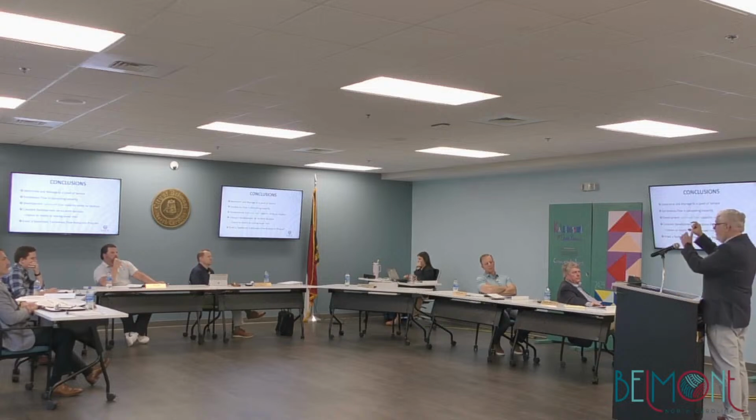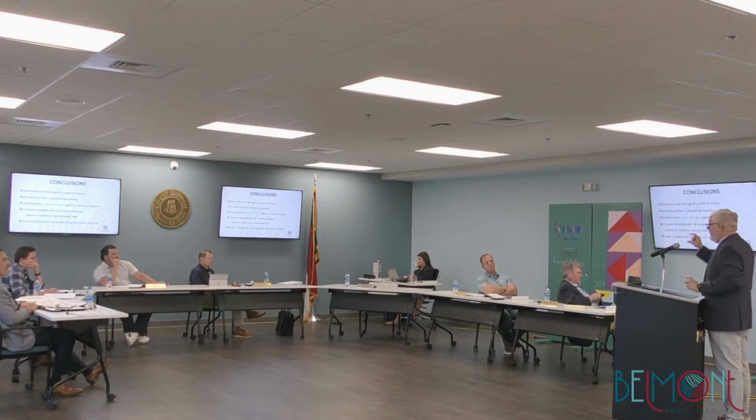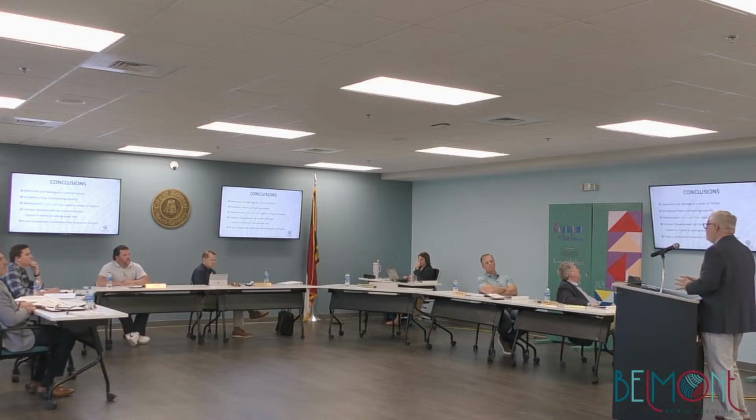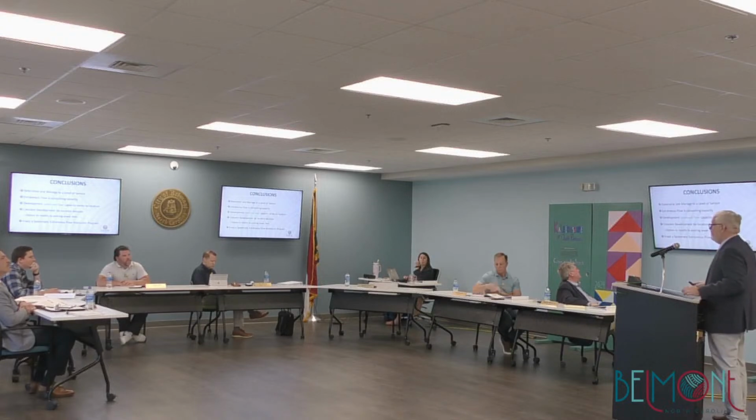If you were to clean all that up, then all of a sudden, any other flow getting in there that typically doesn't get in there in the 2-year, it's only this big. So that's what I was saying, having a target at 5-year is fine, but what you're really trying to get rid of is that first couple of inches of rainfall that's getting into the system. If you can manage that, then I think you can probably manage the other.